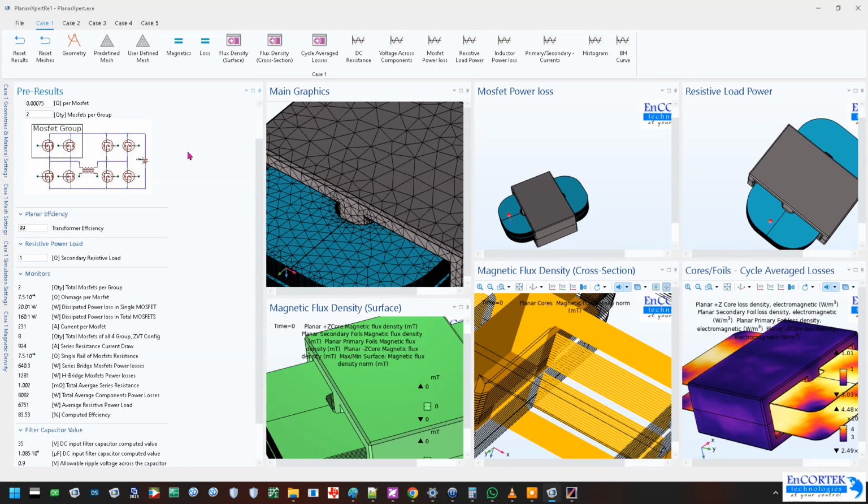So before we run a lengthy hourly calculation, we do not want to waste time. So we can see if everything is fine here, and we make changes. If we know the MOSFET is going to be damaged, we put like 3 MOSFETs, and we will see the current will drop to 150. We look at the MOSFET datasheet to see if it can handle that. We say no, let us put 4, right? And we come to 115. The MOSFETs can handle 150 or around 125 or something, and we say okay, we will use this.